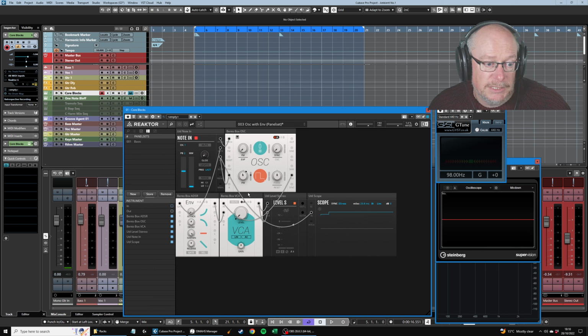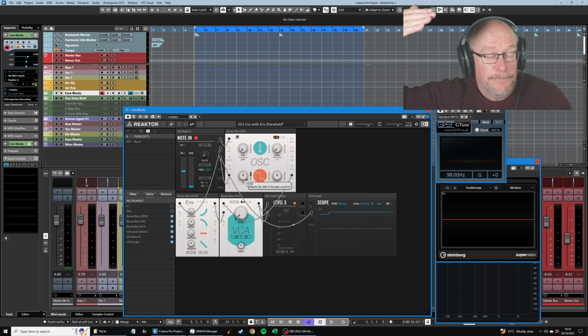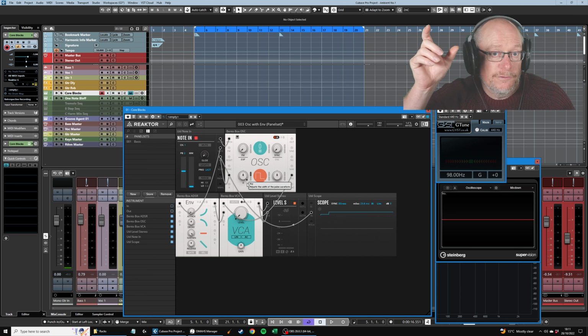And the amount that I turn this thing up, you can see as I basically move the slider up, that's specifying how much change I'm going to allow to be applied to this control. So if I apply maximum modulation, I'm going to set my default position on the knob itself to 0. So ordinarily, this thing's going to output a square wave, but the control voltage that comes from the velocity of the key that I hit is going to add some control voltage, some modulation amount onto this default position of duty cycle positive, the same as negative.